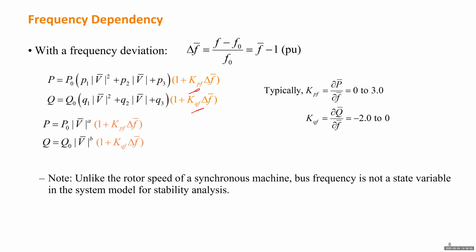So if a load depends on bus frequency, when the bus frequency changes, the load also changes. And that frequency is what this load can see at that location, based on the voltage and current waveform. So even if there's some disturbance which can change the voltage and current waveform, the bus frequency also changes. That also influences this load.